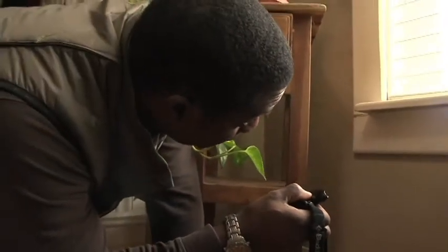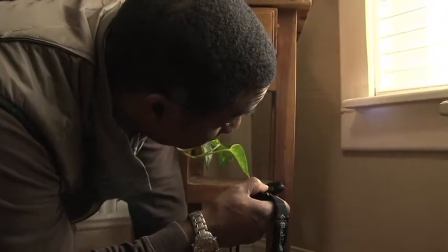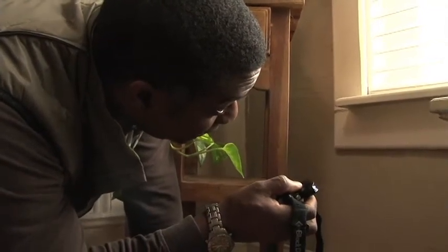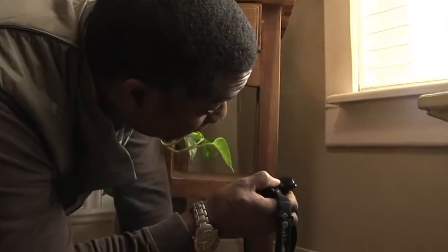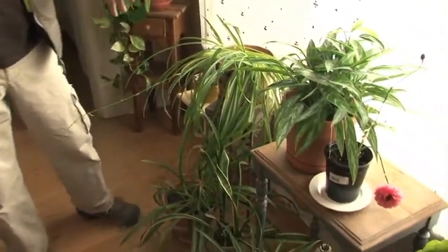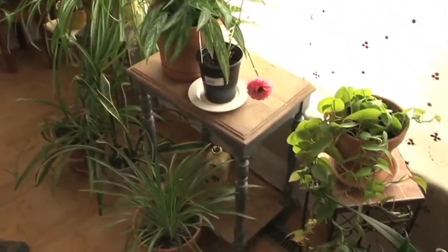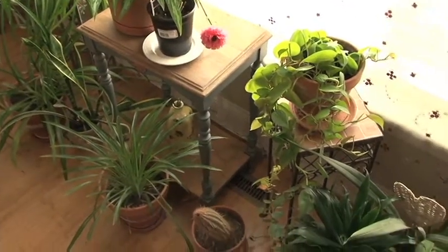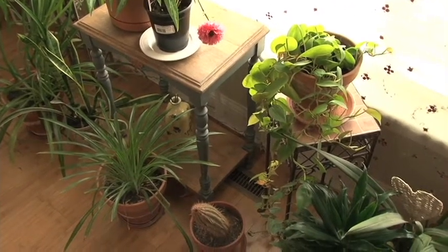All right, so I'm going to check down underneath the window sill to make sure that it's correctly caulked and sealed. And I am looking down here and I see some cracks and gaps between the windowsill and the trim piece here, which indicates to me that we're going to see some air leakage when we run our blower door test. The next thing we run into are these plants. Now, plants are a source of bulk moisture in a home. So we'll want to keep a particular eye out for issues like mold and other water-related issues.